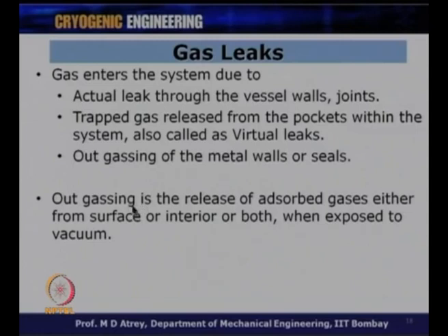Outgassing happens over a period of time, over 6 months, over 1 year, and it all depends on what fabrication the material has gone through. Therefore all these things have to be understood when we start designing for a particular vacuum application, especially where vacuum plays a very important and crucial role.